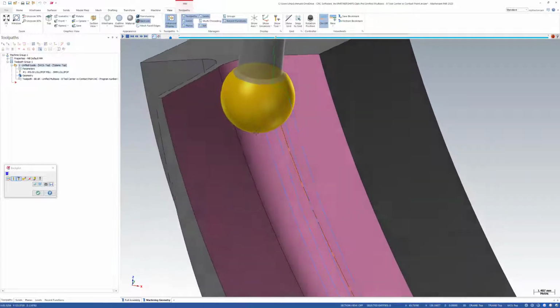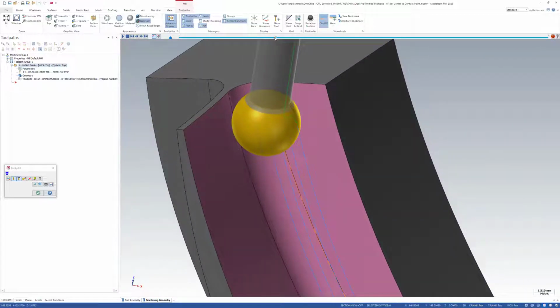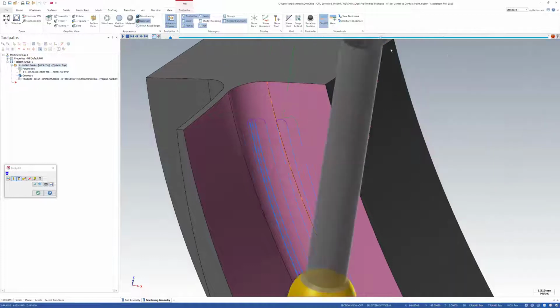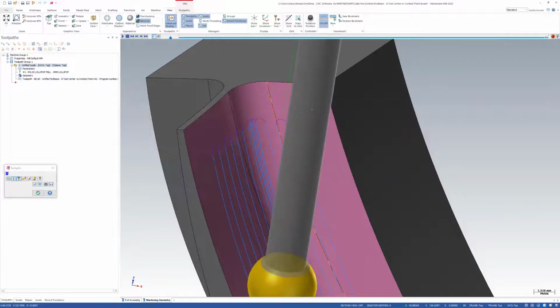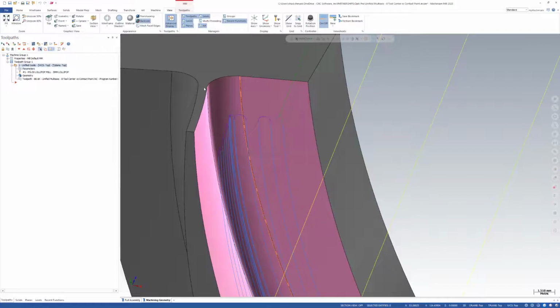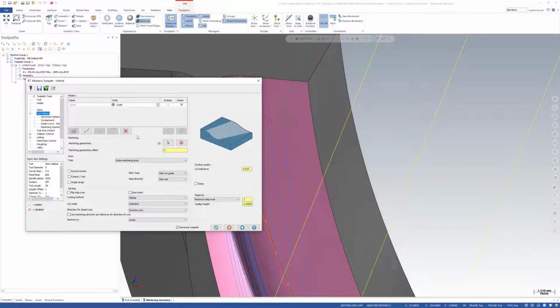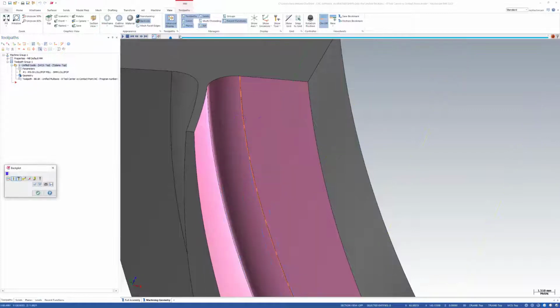So it's worth noting that these blue lines represent the very tip of the tool. If we were to shade this toolpath using tool center point, the step over would at least look a little more consistent. It would still bunch together in this corner though. What's happening is the step over of this toolpath is being measured on the surface. So if you drew a line for every 1 millimeter step over, that tool would reliably contact every single line, basically plus or minus nothing.